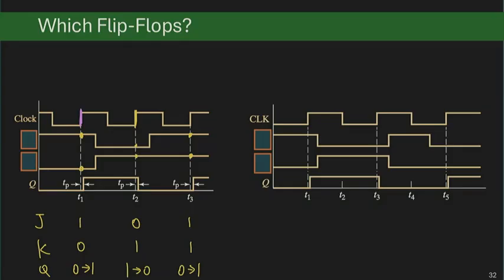And you want to see if that matches the behavior of any flip-flops or not. The answer is probably not. Take a look at that last 0 case. A 0 makes it go from 0 to 1, and it doesn't match any of what we learned.